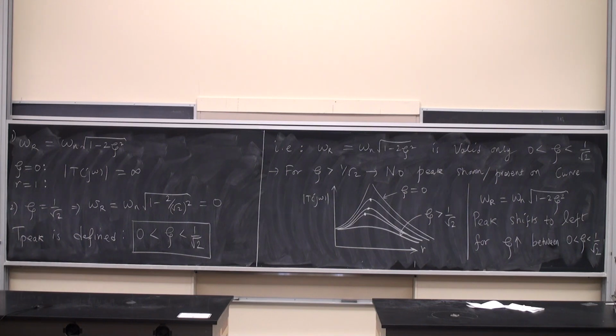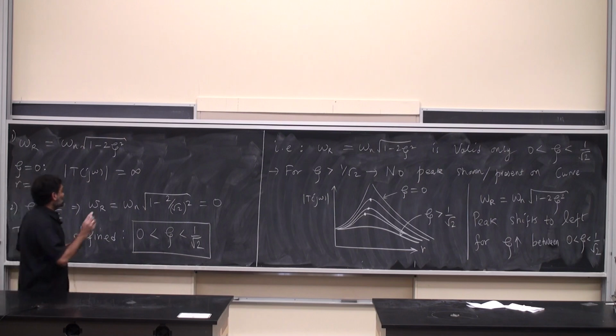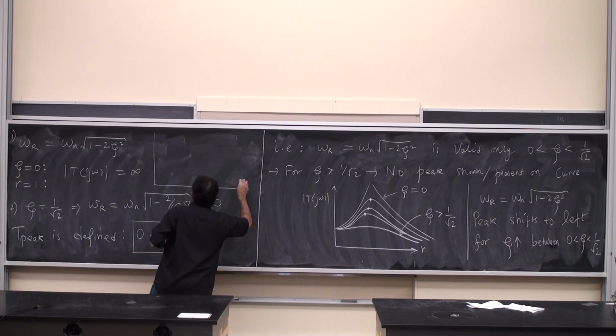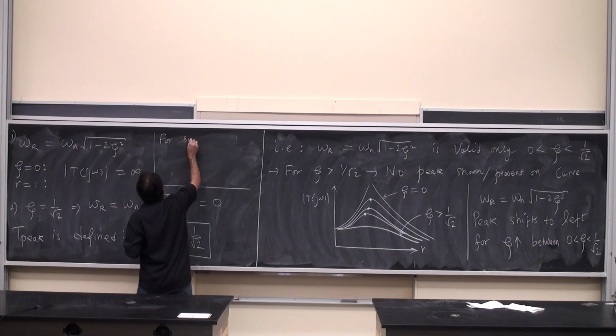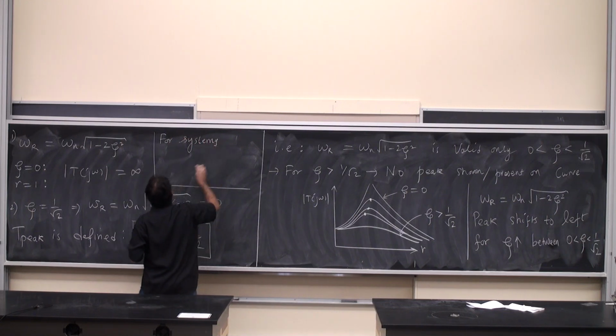As a question: will the expression for the resonant frequency be the same even if we weren't looking at the capacitors specifically? The expression need not be the same depending on the numerator dynamics. Okay. So this is for this particular scenario. And this, in some sense, is most representative of many mechanical systems without numerator dynamics. Right, absolutely. So I should make a point, that's a good point to note here. This is for systems without numerator dynamics.